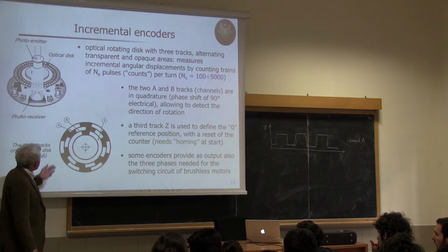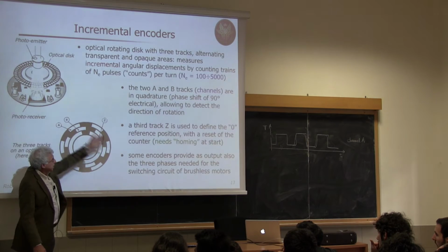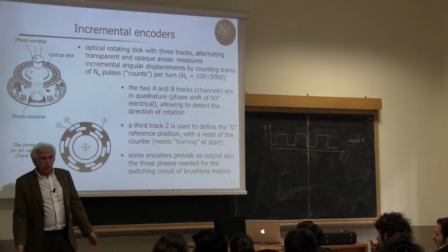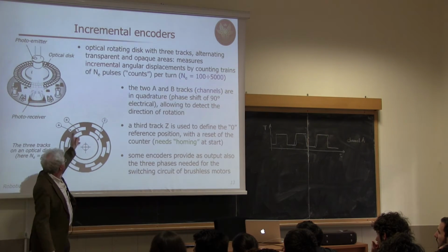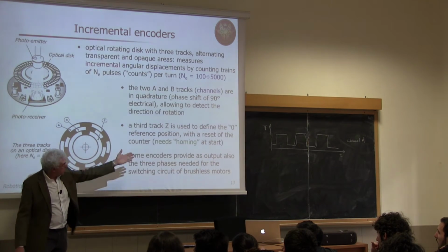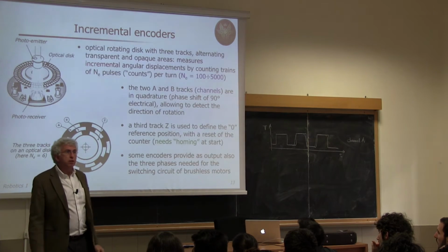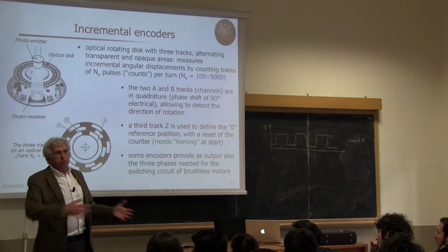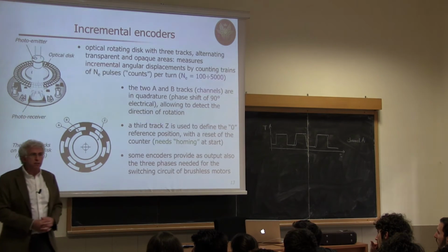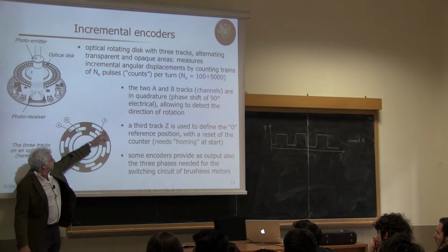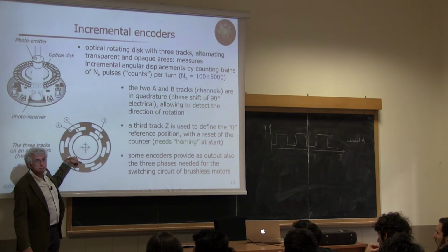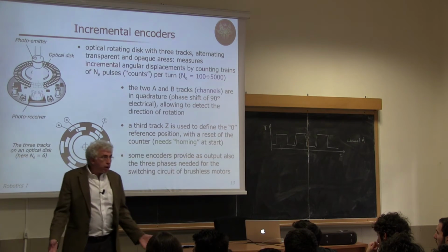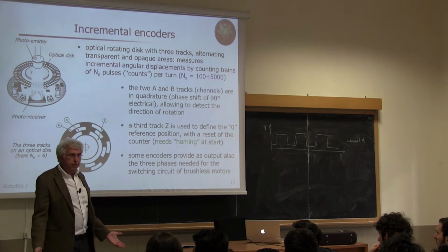Anyway, while rotating, you feel this train of pulses, and when you have done a full turn, in this case, you have seen 6 times the leading edge of those pulses, and so you can count an increment of 360 degrees. Of course, the more sectors, the more impulses per turn you have, and the more accurately you can measure increments.